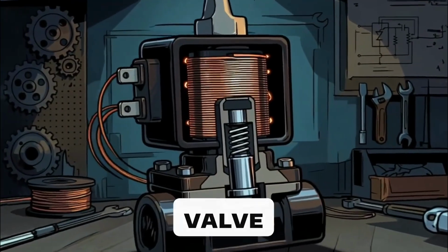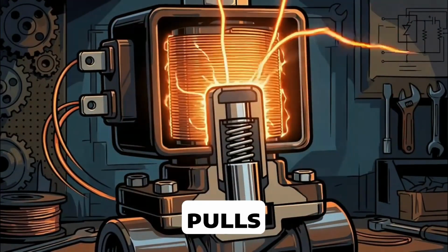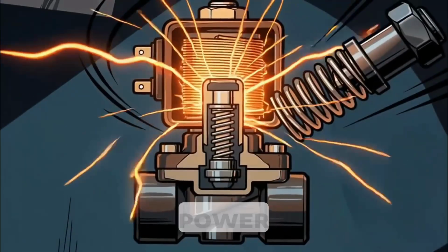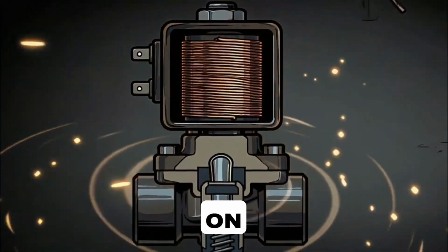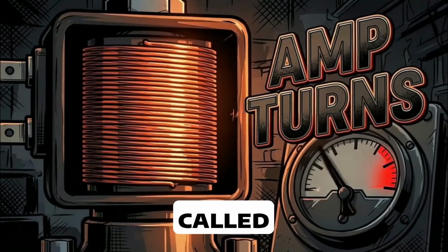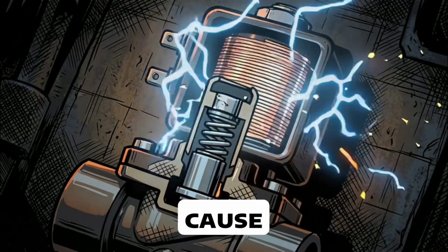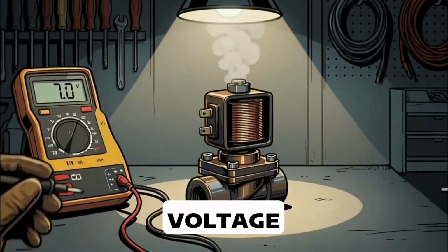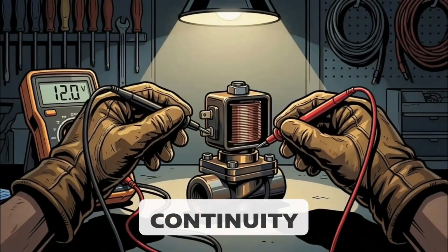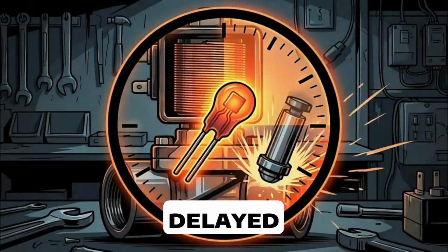A solenoid valve uses current through a coil to create magnetism that pulls a plunger inward. When power stops, a spring returns it. Strength depends on current and number of turns, called amp turns. Low voltage or shorted coils can cause chatter, weak pull-in, or failure. Test with voltage drop across the valve or continuity with an ohmmeter. Some use thermistors for delayed action.